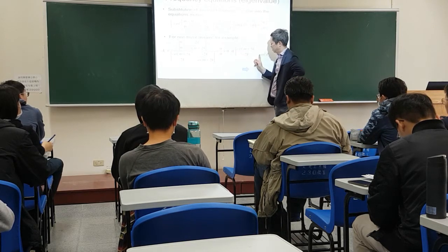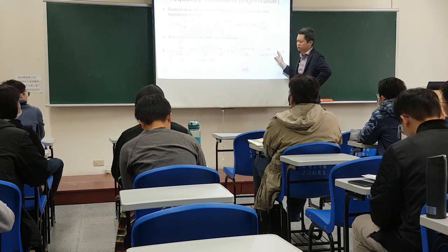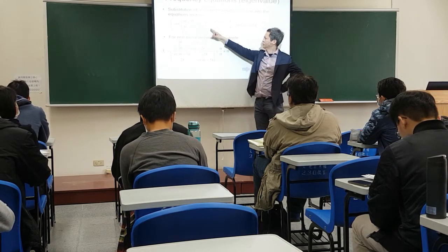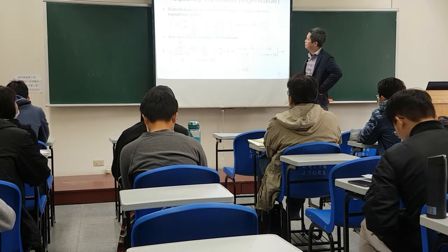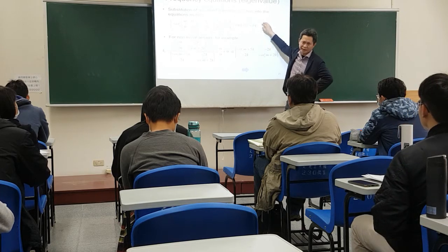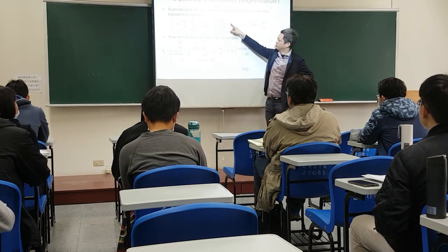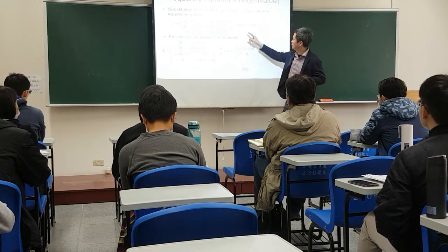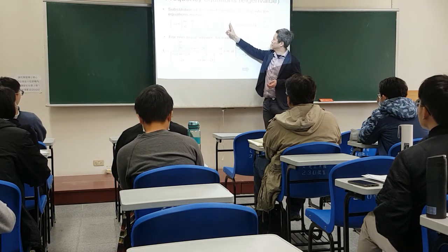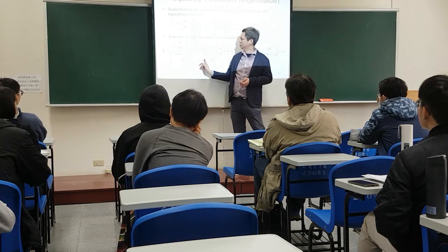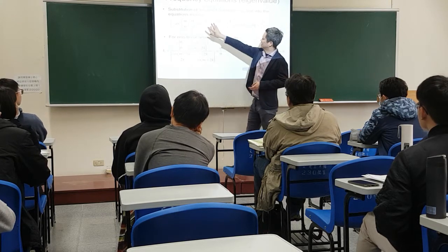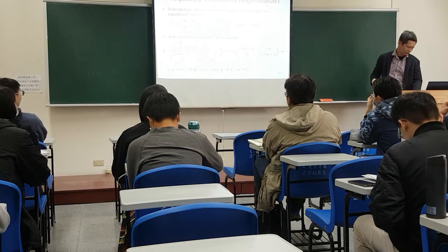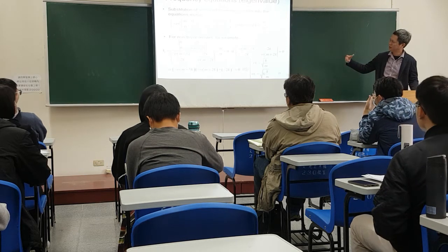So that you can find the critical condition, the so-called frequency equation, when the amplitude is not zero. The only condition to find a non-zero amplitude is for the denominator to be zero, which means setting the determinant of your system matrix to zero. Then you find your resonant frequency. Okay, so this is how you find the natural frequency.